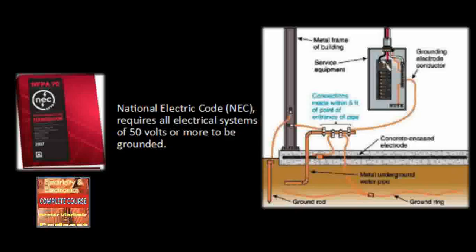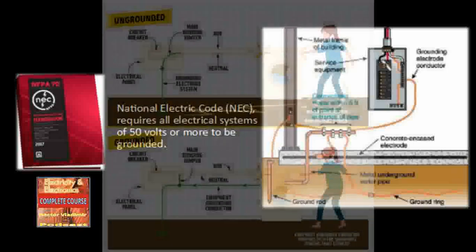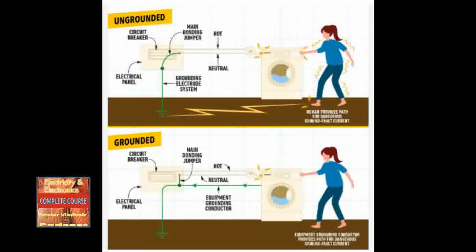Some devices are double insulated, which means the outside enclosure is not grounded. A person using the device will not be in contact with the ground circuit by using the device, and thus will most likely not experience electric shock should a ground fault occur. Figure 2-21: when a person touches an energized conductor, his or her body completes a circuit to ground.